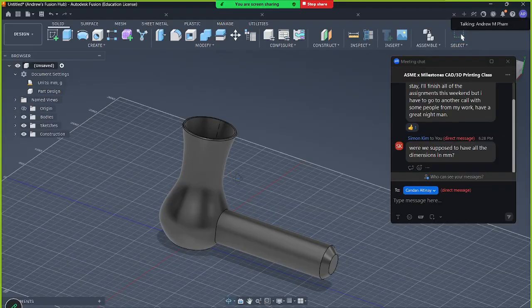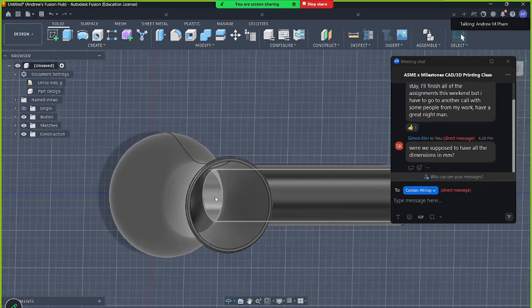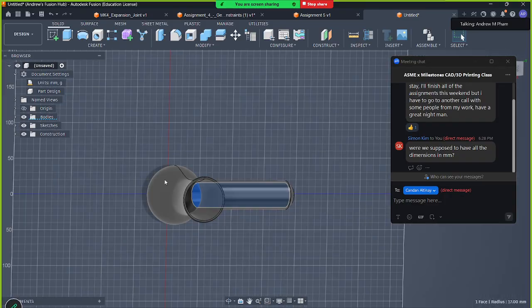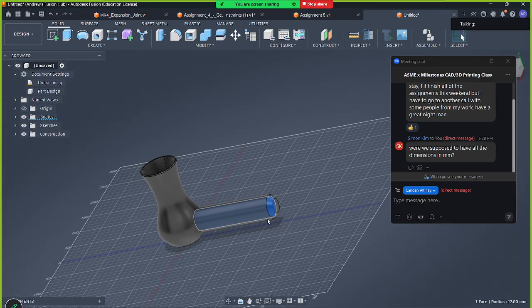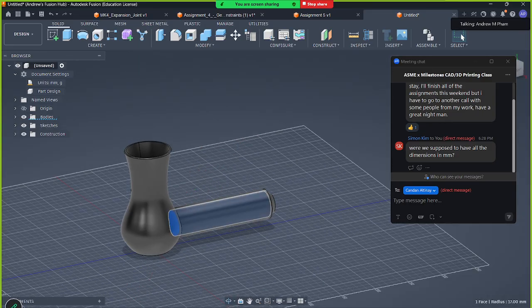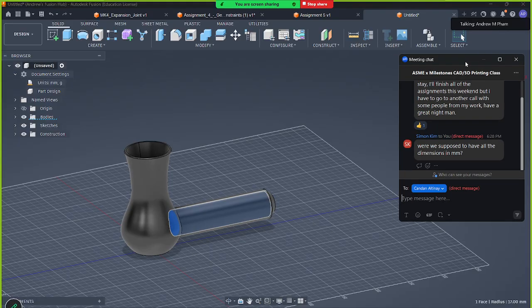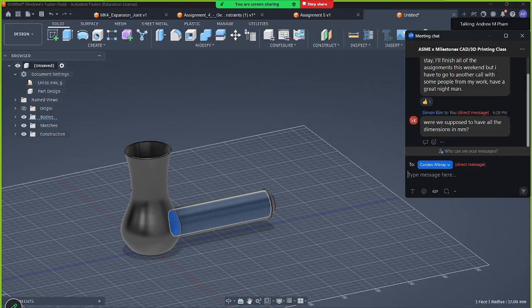And when I do that, if I look very carefully, you can see the inside of this handle is also shelled out, right? I didn't add any more features, but I've created a different kind of geometry internally, right? So the order of which you create your features can sometimes be important. So it's a good thing to keep in mind when you're modeling things. If you need certain geometry to be flexible, then you might want to make sure that some things aren't dependent on it.